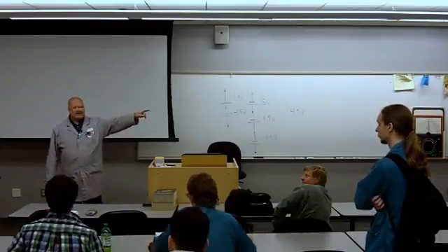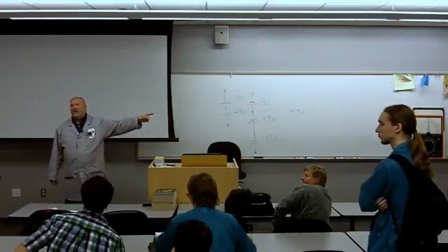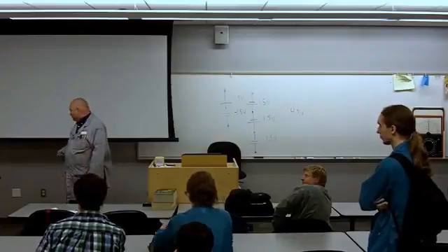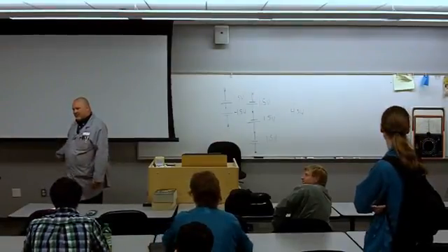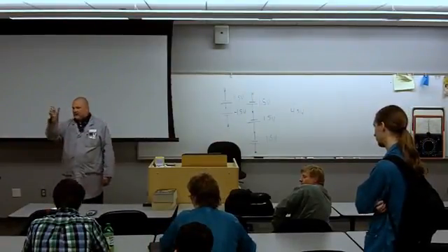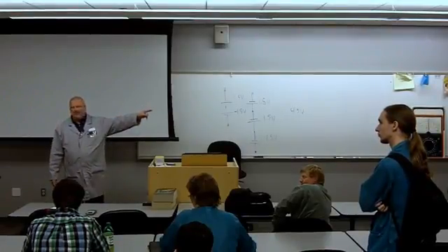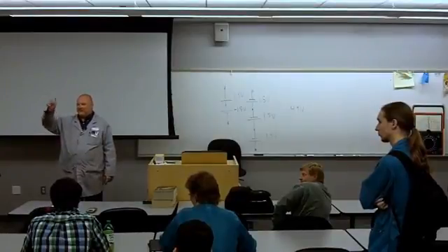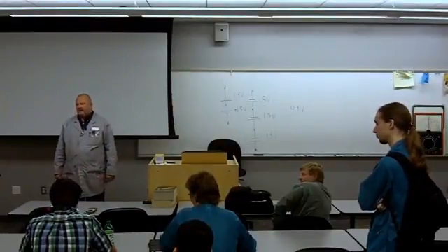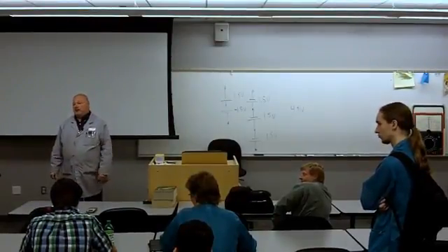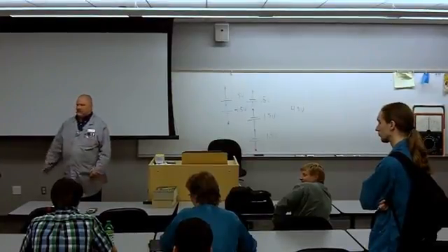Those two should be connected back at that box. So between the hot lead and ground, and between the hot lead and neutral, I should end up with the same difference in potential. Then going with a multimeter to that box, I should get that same difference in potential across the two. And that basically lets me know that the ground and the neutral for that particular circuit are valid.